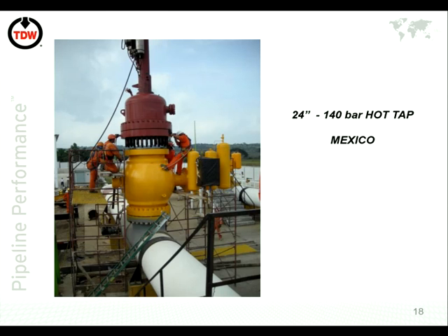The big difference being, if you think of a drill, if you think of that sandwich valve, which was quite thin, the drill has to pass through that sandwich valve before it starts drilling the pipe. Similarly, it has to pass through this whole valve here before it gets to the pipe. You can't see it on this picture, but what it means is that the tapping machine is extremely long because it has to have a lot of travel to get onto the pipe before the drill occurs.